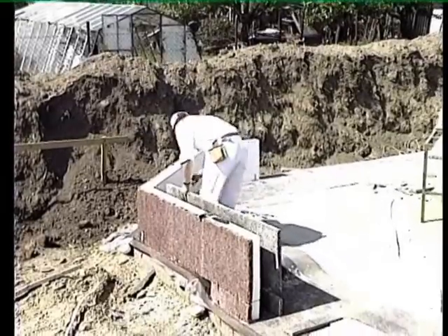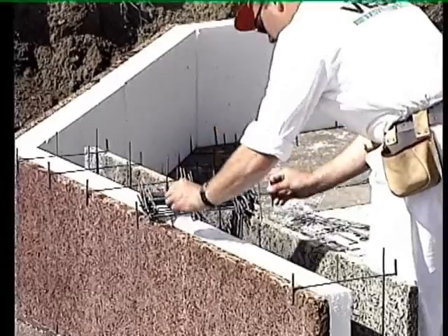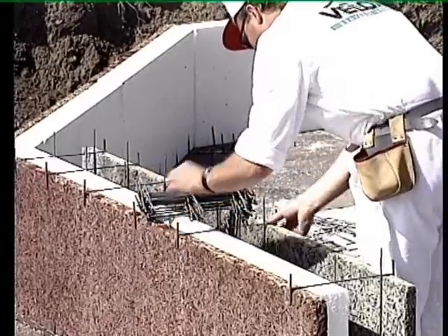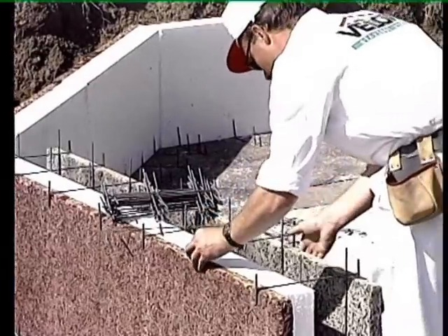A two-sided tie is attached to the upper edge after both casing boards have been installed. 8 ties are used along a board joint of 2,000 millimeters.